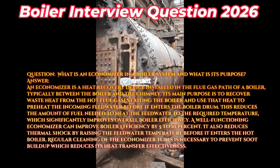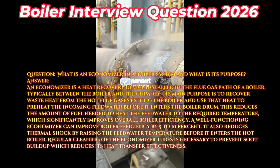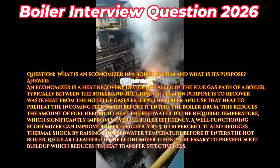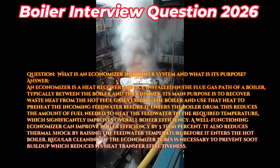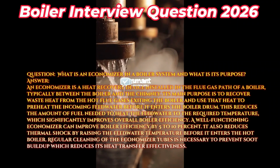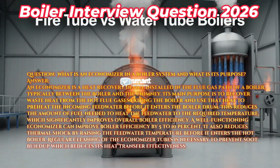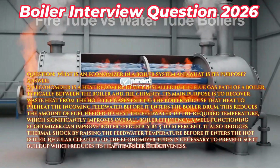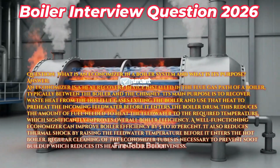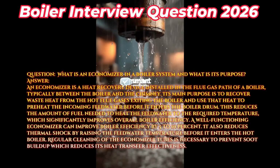This reduces the amount of fuel needed to heat the feed water to the required temperature, which significantly improves overall boiler efficiency. A well-functioning economizer can improve boiler efficiency by 5 to 10%. It also reduces thermal shock by raising the feed water temperature before it enters the hot boiler. Regular cleaning of the economizer tubes is necessary to prevent soot buildup, which reduces its heat transfer effectiveness.